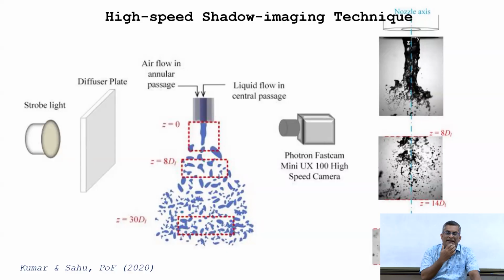On the other hand, let us say you have a resolution of 3 micron while you are measuring particles of size, let us say 40 micron, then you can very accurately measure the size. But what happens, to achieve very high resolution, we have to go close to the flow field or use lenses such that the viewing area is smaller and smaller.